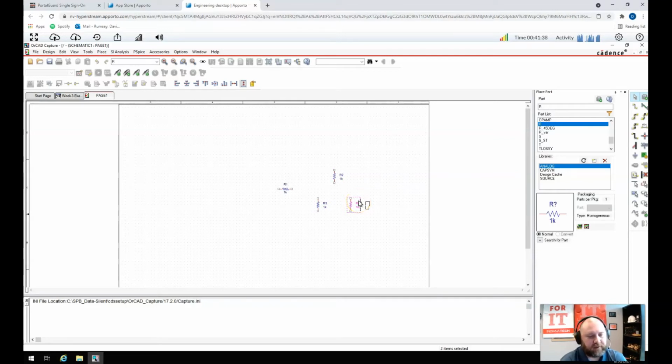Now, that's purely for my own perspective benefit. I don't have to technically do that as long as the connections are made properly. It doesn't matter if the resistors are rotated vertically, horizontally, or 45 degrees, whatever. It doesn't matter. So to finish placing a component, because it looks like I'm still wanting to place resistors, you hit the escape button.